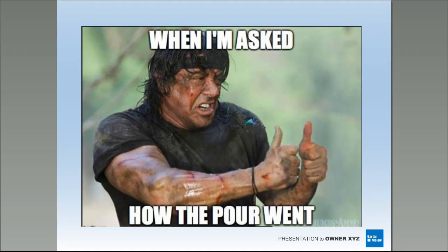I've got one from Clark. Does fiber affect gloss? That's a tough one, depending on the dosage and depending on the fiber. Typically, I do not see that. Could it? You'd have to have a pretty high dose of fiber to actually affect the gloss, and you'd almost be taking over the cement content or the aesthetics of the slab at that point. So, no, typically I would not say fiber affects gloss, in my opinion.